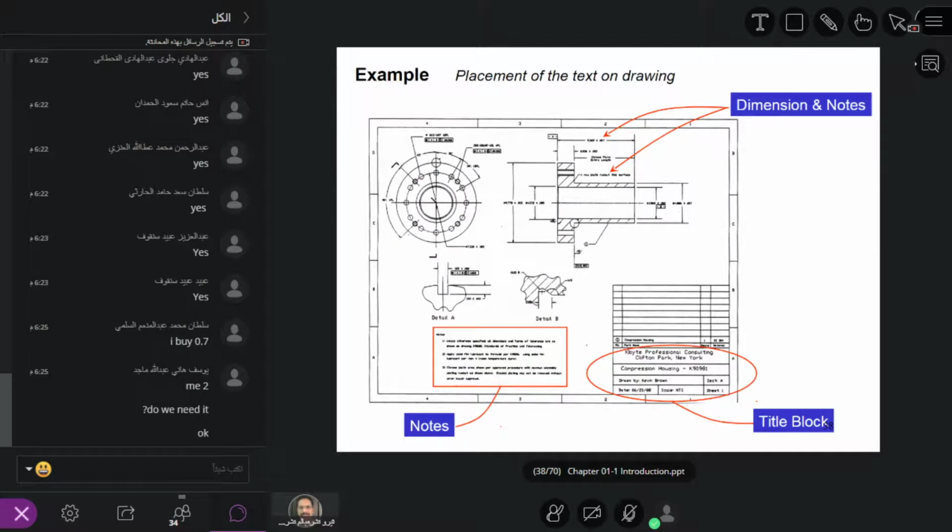So this is an example of a typical technical engineering drawing. This is what you're going to use. Not necessarily these lines you need to draw, but definitely the first thing you have to do is to draw the marginal boundaries. If this is your drawing table, like I mentioned earlier, you have to get 25 millimeters here, and then another 5 millimeters, 5 millimeters.